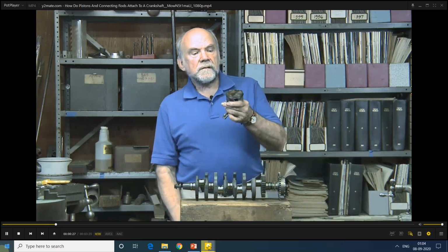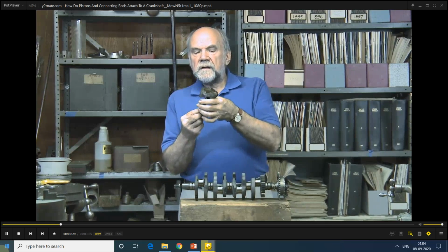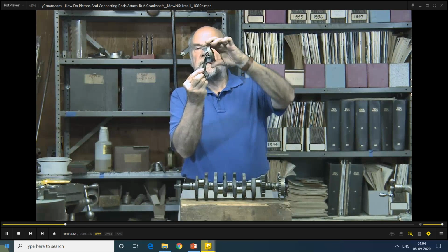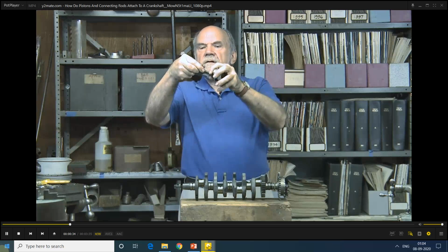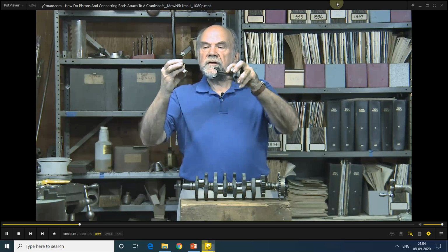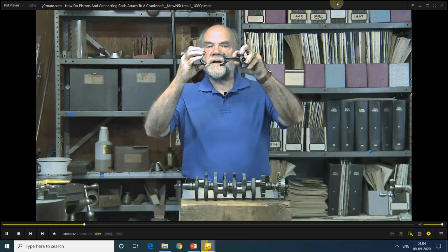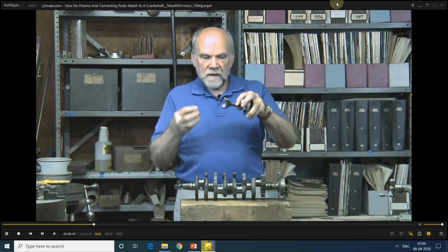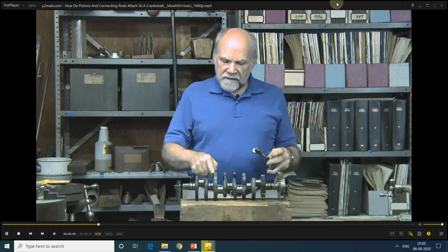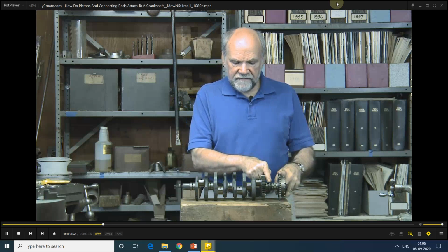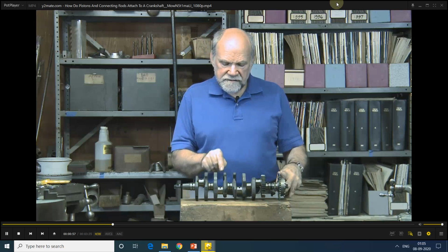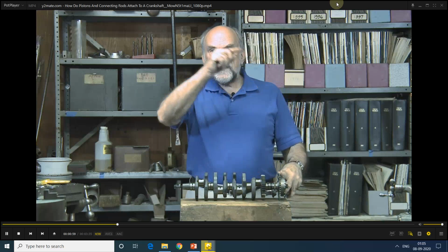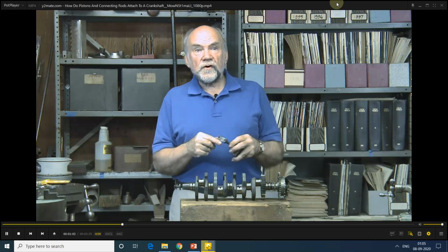Now here is a piston. The wrist pin connects the piston to the connecting rod. The connecting rod is assembled on the crankshaft in two halves. It is split and bolted. It has these alignment pins which go into these holes. Now, the main bearings, which are these 5, simply revolve around their own axes. The crank pins are offset and they describe circles of their own.